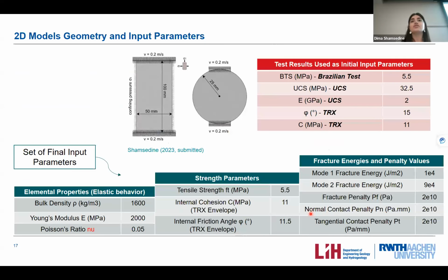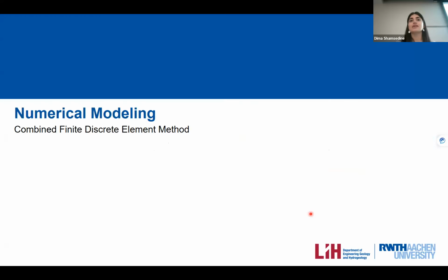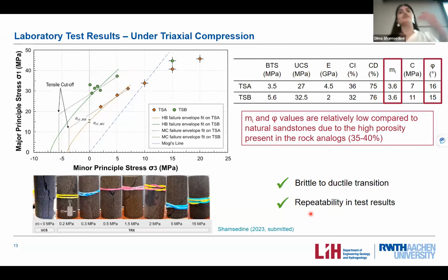No, we haven't reached the creep behavior in our experimental tests and triaxial tests because the duration of the test was around 30 minutes overall. So we applied the isostatic confinement in a few minutes, and after keeping this isostatic confinement constant, we started applying the axial load, and the samples directly failed.